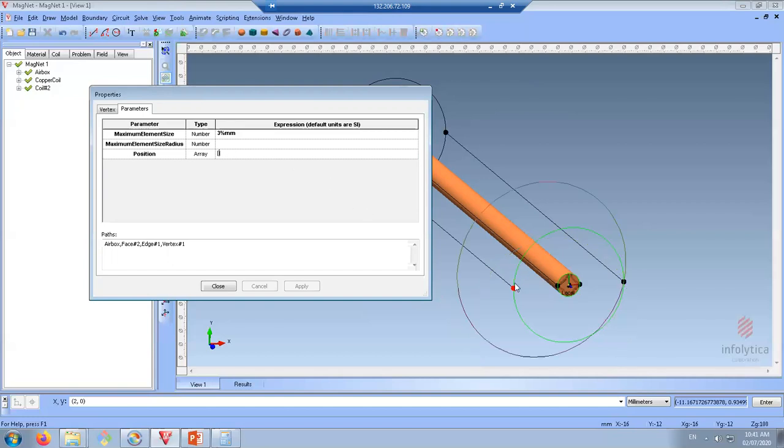That vertex, I mean this one, is located on the negative side of the x-axis. So this is how we use the parameters that are defined in the Parameters tab of the global model. Airbox radius. Using this percentage sign basically adds a reference, so we can refer to the parameter that is already defined.